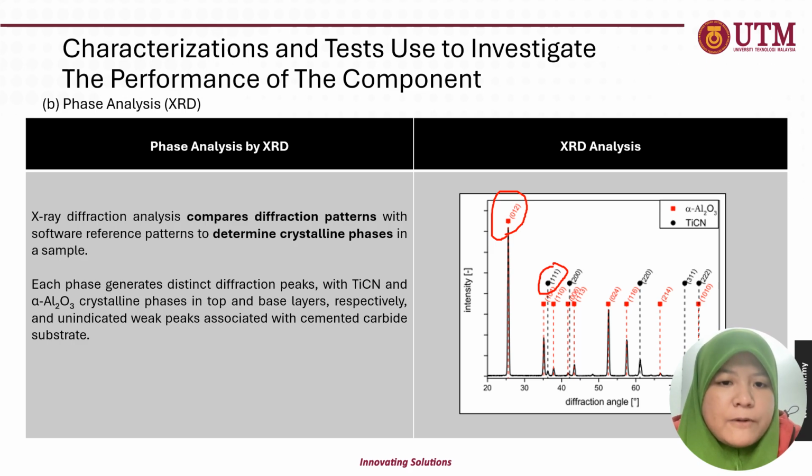Compared to EDX, which is elemental analysis and shows only aluminium and oxygen, XRD can show compound materials. From here we can confirm what type of coating and substrate were used for this sample.